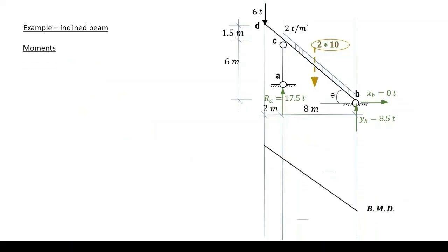Bending moment diagram. We compute one moment at C here, and plot it perpendicular to the center line, as all other diagrams were plotted perpendicular to the center line. So we have MC computed from the left part equals 6 by the arm perpendicular to it, 2 meters, making 12 meter tons with a tail of the force heading upwards.